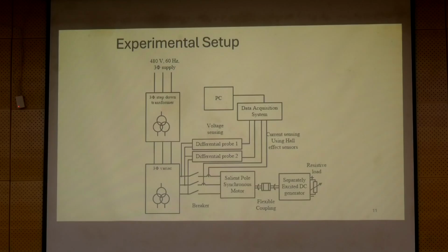Nowadays, thermal imaging is also being captured. Temperature sensor outputs are also being captured. So if you have a good enough data acquisition system, which is sometimes quite useful to invest in, you can capture a lot of signals simultaneously. Now, the simultaneous capturing of signals is quite useful from a machine learning perspective, at least initially. Later on, you can capture them one at a time and see their impact. But if you can capture all the signals simultaneously, then it helps in your machine learning implementation. Okay?